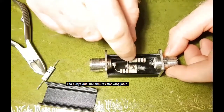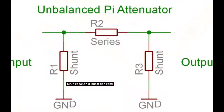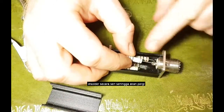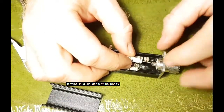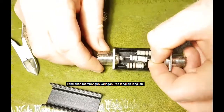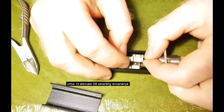We've got two 100 ohm resistors dropping down to ground in the center, and we're going to have a 75 ohm resistor soldered in series, so it will go from the hot terminal here to the hot terminal on that side, and we'll build a full pi network for 10 dB attenuation.